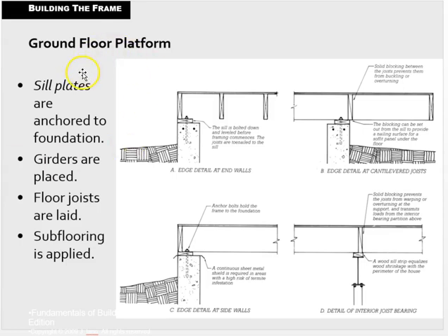So these are just some more details of what's happening at the connection at the foundation. So they're anchor bolts, sill plate, and joists. Here the joists are coming at us and cut in sections. An important point on this slide, very important point, is that here we see an X through the joist. That tells us that it's a continuous structural member. And here we have a piece. So here's a joist, not coming at us. We're not seeing this in section. It's running in this direction over the sill plate, and it's creating this cantilevered condition.